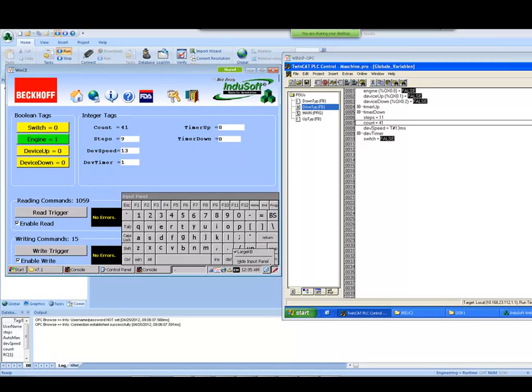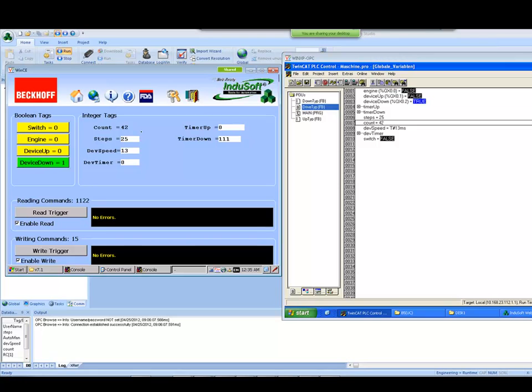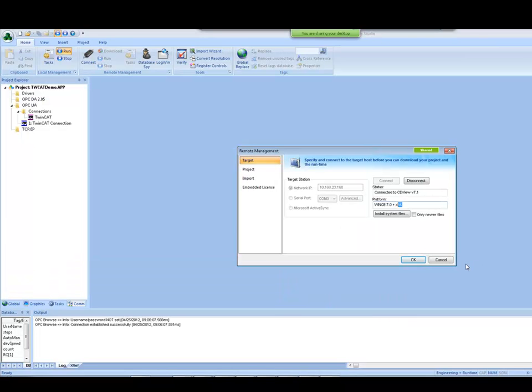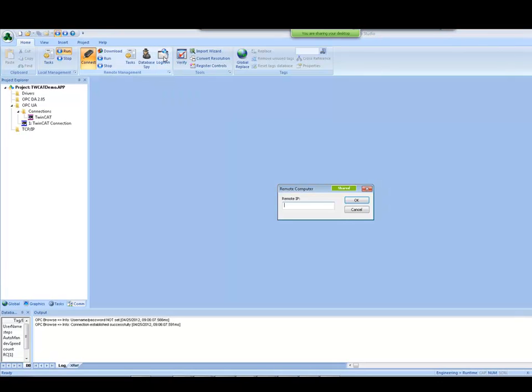Okay, and that on Windows CE using the UA technology that we were just talking about now. If I want to debug the communication that's going on in the Windows CE from my development environment, I'm gonna click here. If you see on the mouse, on the back I still have the InduSoft development environment, so I can click on login. On my login here, enter the IP address of my Windows CE device.